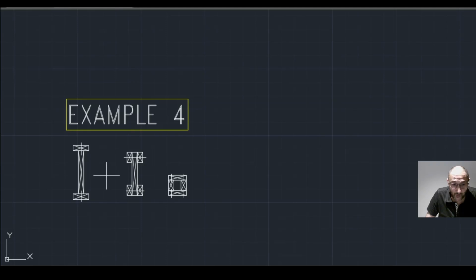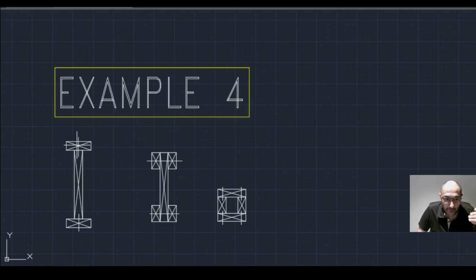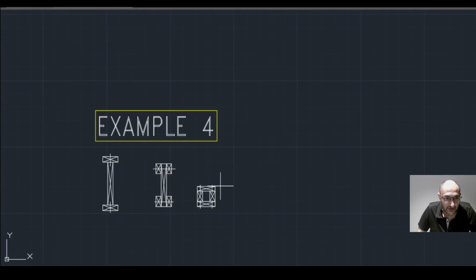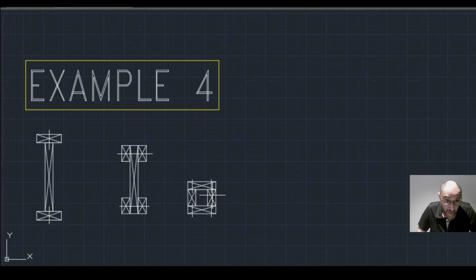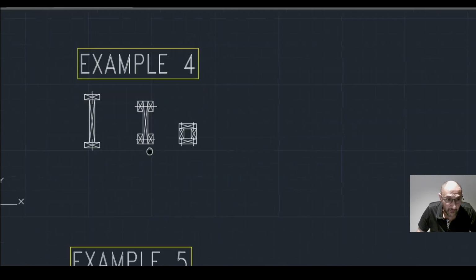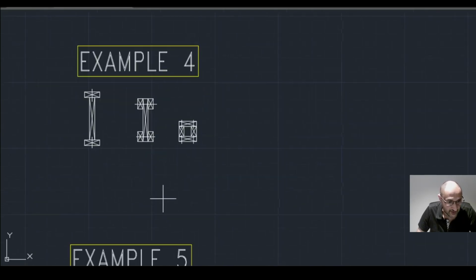In the first diagram, we would need to consider the shear stress in the top and the bottom plane where the elements are in contact. But in this second diagram, we need to consider the shear stress along both sides. And in the second diagram, it's probably more convenient to use it as a flexural member. In that boxed-up section here, we check the shear stress on the sides where the elements are in contact to work out the capacity and the number of fixings required to unify the section.